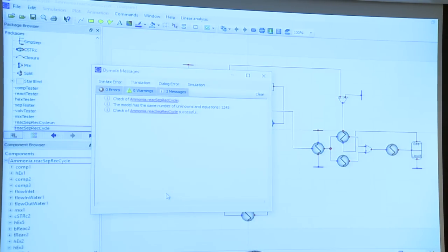We don't have the gradients. The reactors are modeled as simple CSTR cascades because we want to have a one-level system. We don't want to go to multiple levels where we have to solve in each. If we use it for optimizations, we don't want to solve a differential equation in each optimization step.